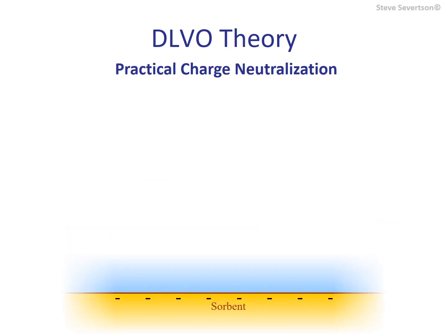As discussed previously, particles in aqueous process streams commonly carry a negative charge. Commercially, such anionic colloids are often neutralized with cationic polyelectrolytes. For charge neutralization, the charge density of a polyelectrolyte is more important than its molecular weight, and high charge density, low molecular weight polymers are commonly utilized for this application.